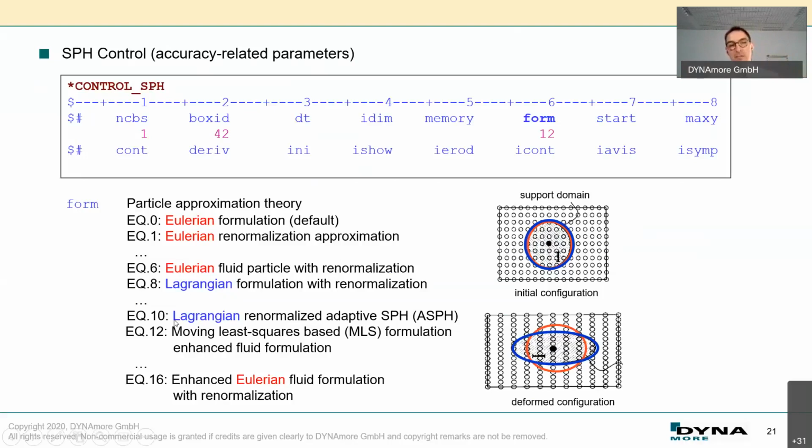There's another one, commonly used for structural deformation, which is the adaptive SPH method. Also here, the Lagrangian kernel is deforming, but the deformation is adjusted based on the direction of the deformation. So it's more like there's an anisotropic tensor in it, which governs the shape of the Lagrangian kernel. That way, where we have a large change in geometry, we extend the kernel, and we do not do so in the other directions. This is the idea of adaptive smoothed particle hydrodynamics.